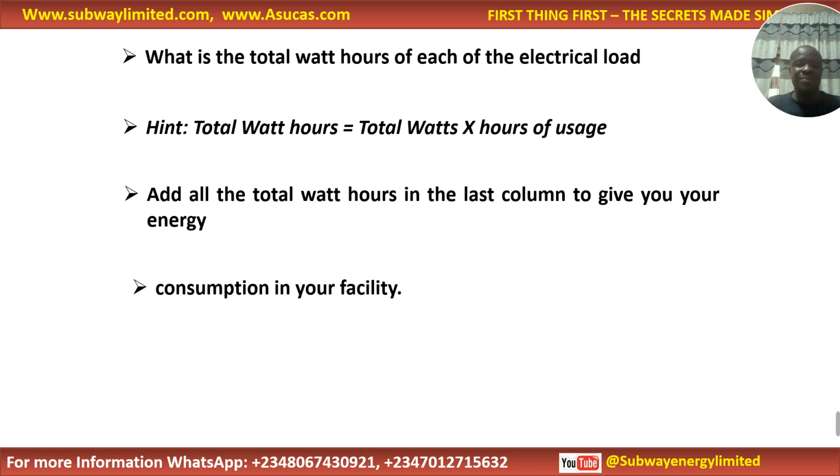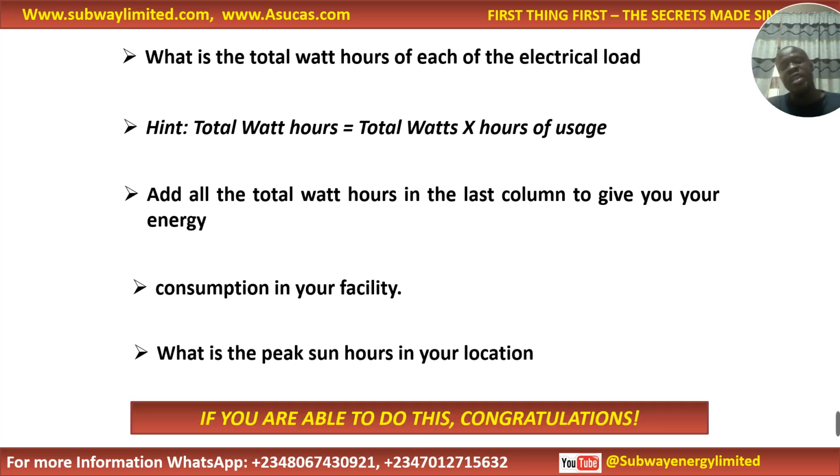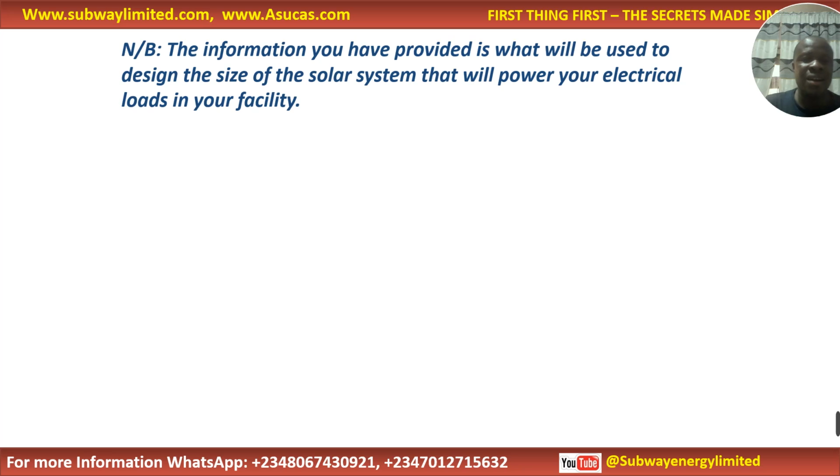So for consumption, add all the total watt hours in the last column to give you your energy consumption in your facility. So what is the peak sun hours in that particular location? If you are able to do this, congratulations. If you are able to fill the form and supply us with all those details, congratulations. One thumb up for you. You are following us. So we are moving ahead.